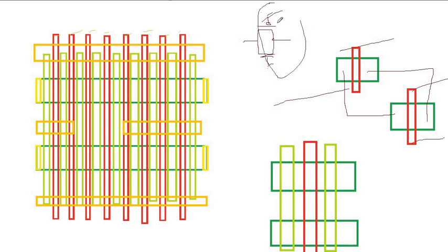Assuming that this is the connection I'm trying to implement, this is separate, this is separate. Now when I'm placing these two transistors next to each other here, I need to cut this, else it would be an incorrect connection. So what I will do is a cut poly layer over here. I would apply another type of base level cut layer, like how we have got CMD, cut MD. To cut the poly, we have got a layer called CPO layer, or cut poly layer. So you are chopping off this poly.